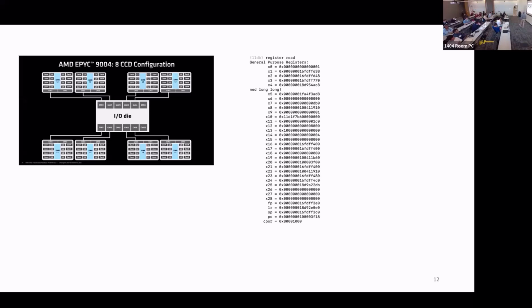There are 8 die. These are essentially 8 times 8. Each of these is effectively very close to what I would think of as an 8-core laptop chip. And they've got a multi-die module, where each die has L2s and a shared L3, but then coherence between all of these, all connected to a base I/O die that talks to the memory, right? So you can see this is actually pretty complicated, and you get all sorts of effects if you're exchanging data between threads in the same die or between different die. And we've seen all sorts of issues with Frontier related to this.